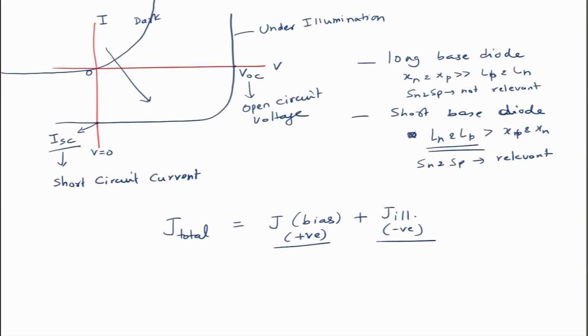And we also looked at the effect of various parameters on the quantum efficiency. The quantum efficiency shows a behavior like this. So, perfect quantum efficiency would be something like that. This is quantum efficiency as a function of wavelength. Whenever the quantum efficiency reduces on the lower wavelength side, it means the top of the solar cell is playing an important role, so this would be the top part contribution,